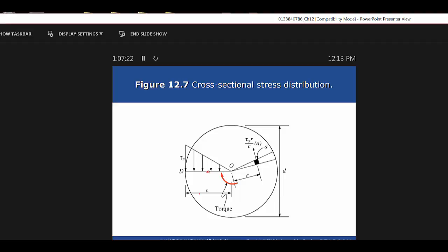And let's see, what else does it say there now? That number ended up being 8,050 psi. Now it does say the shear stress varies linearly from 0 at the longitudinal center of the shaft to 8,050 at the outer surface. Shear stress at the inner surface can then be calculated by the proportion. They're talking about the ID, aren't they? The inner diameter, that is the inner surface. So it's 8,050 divided by 2, because the 2 is half of the 4, isn't it? So there's 4,025 psi max shear stress going on the inside of that pipe.